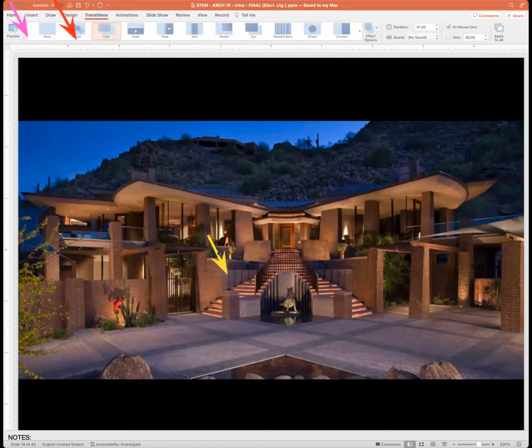Now, what I wanted to show to you here very simply is the town let us do something which is in violation of their code. They let us put this light here underneath the tread, lighting the riser here at the stair. And the reason the town let us do that was because I took the time to do a mock-up and to show them what it would look like.